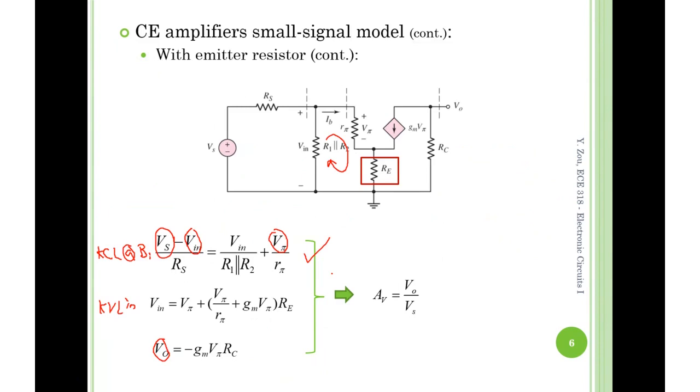Well, I have emphasized this since the beginning of the semester. What you learn from 235 is you should establish such concept or confidence that KCL, KVL always work. However, current and voltage dividers don't always work. They have constraints. You need to be able to clearly identify an independent single loop or single pair. This is what we learned from 235, and be very careful when you use them. Any questions?